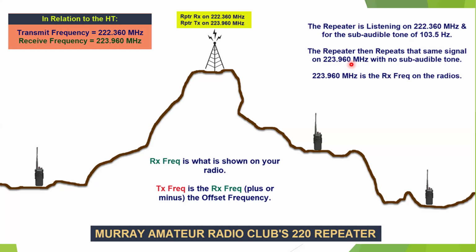The repeater then repeats the same signal that he receives on 222.36 and retransmits it with no subaudible tone. And we're going to learn that you can configure repeaters to also transmit a tone, and it doesn't have to be the same tone. It can be a receive tone of 103.5, which is our transmit tone.